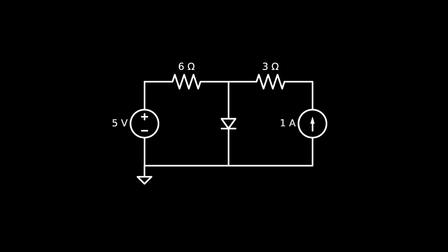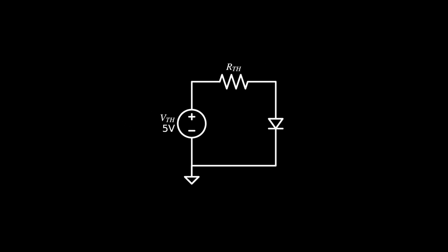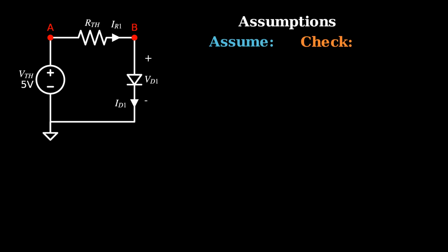For now, with a single diode, we can treat the diode as the load and Thevenize the rest of the circuit. We would like to use the linear analysis methods we learned in our circuit analysis courses, if we can, but we are coping with the nonlinear VI curve of the diode. To bring the linear methods, namely nodal, back into play, we will make some linear assumptions, analyze the circuit using those assumptions, and then check those assumptions against the shape of the diode's VI curve.